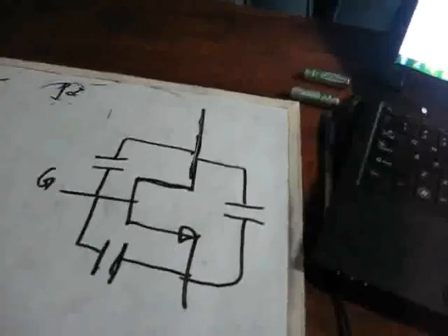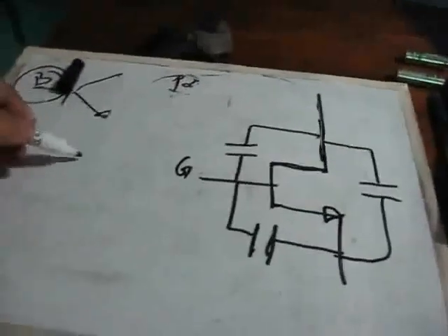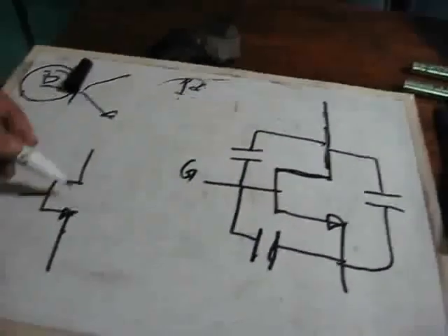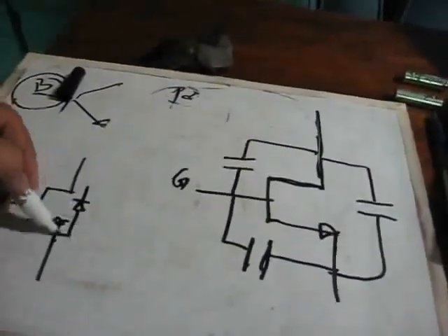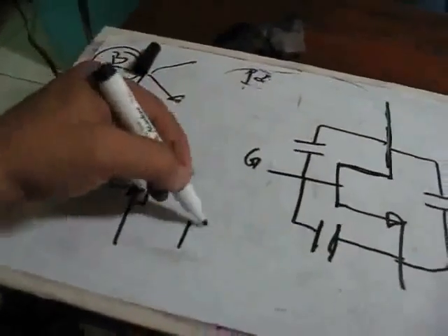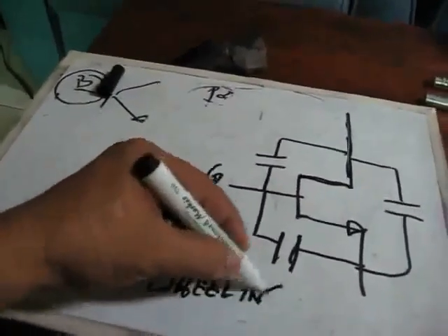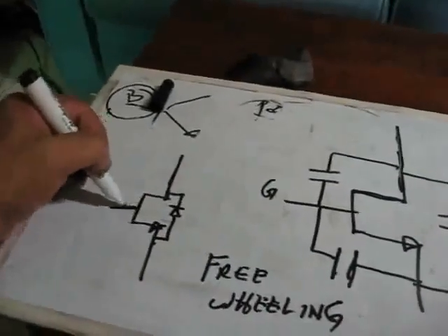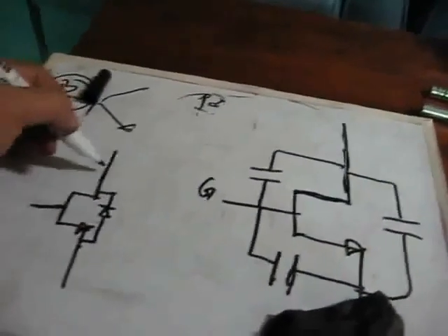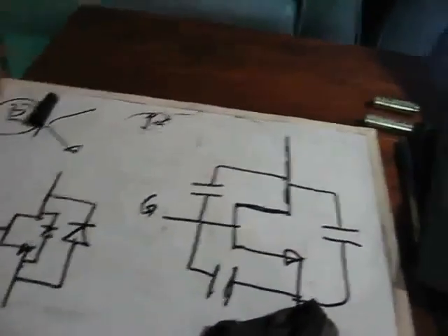Somebody must find some way how to do it. Maybe I'm not good at using the IGBT actually. But if you want, I give you some idea. Let's say this is the IGBT, and inside there is always a freewheeling diode. This freewheeling diode was there because of the manufacturing process that really requires it. But you must support that. You must put an external freewheeling diode, which is a little bit bigger.